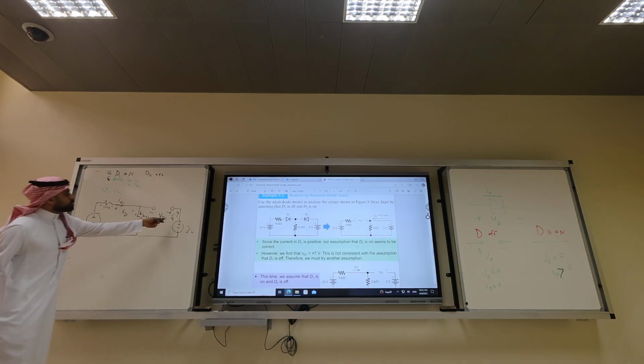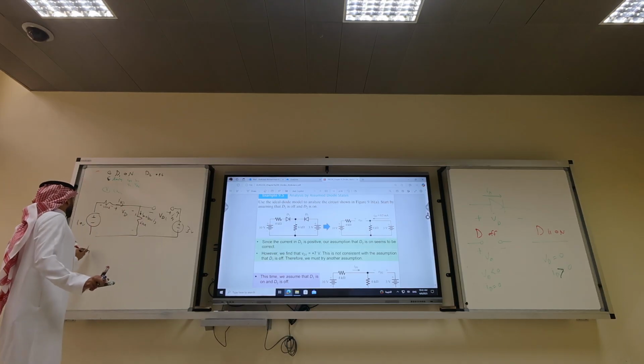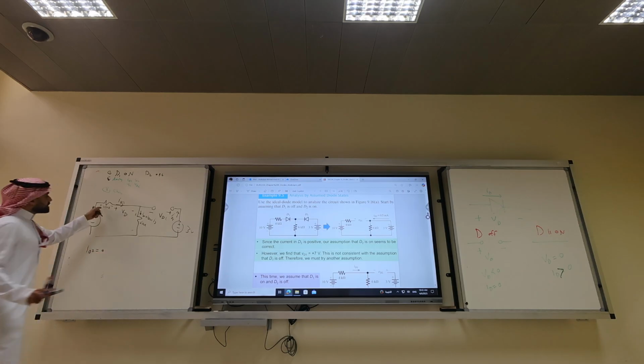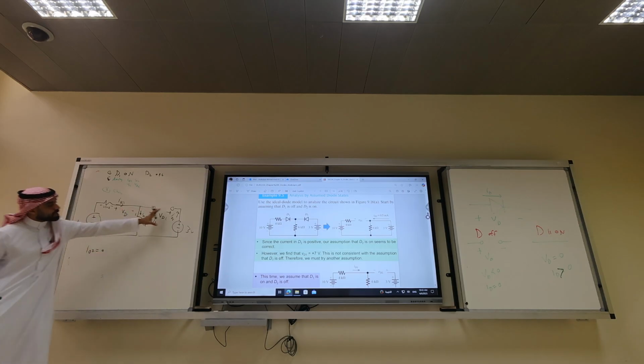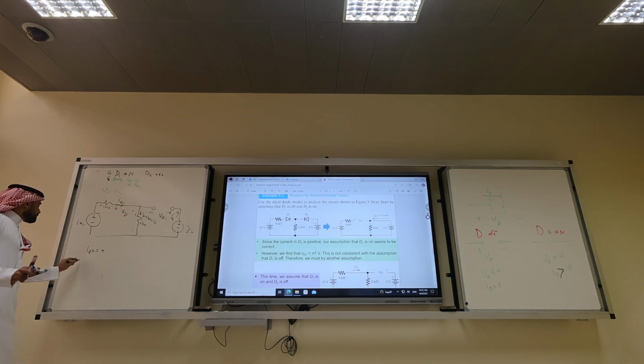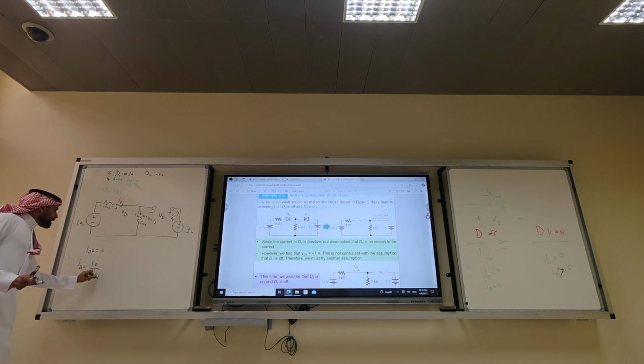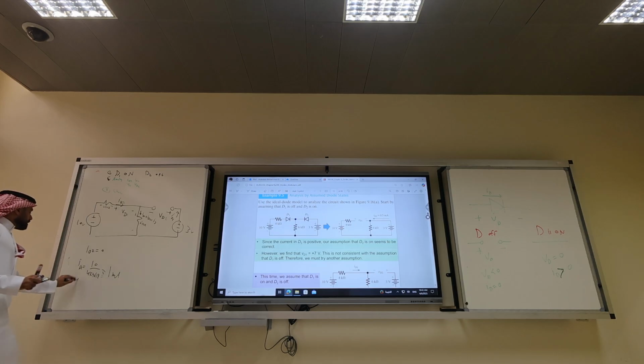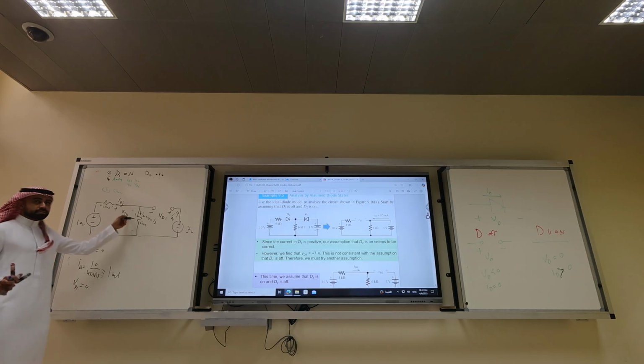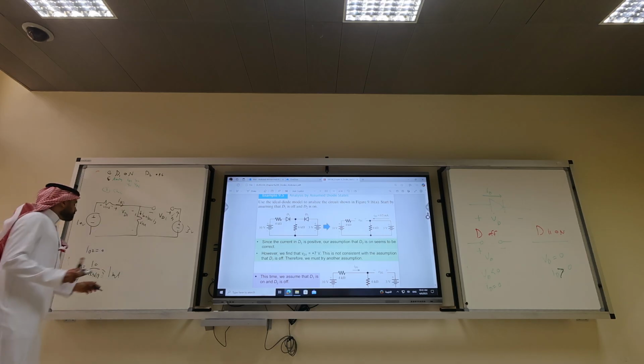Okay, what is ID2? What is ID1? Because this is an open circuit, ID1 is simply what? 10 over 4K plus 6K. What's the answer? 1 milliamp. So what is VD1? 0, short circuit. What is VD2?